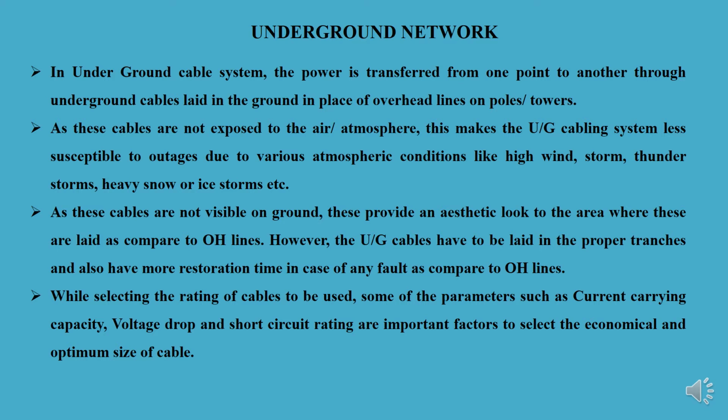However, the underground cables have to be laid in proper trenches, and there is also more restoration time in case of any fault as compared to overhead lines. So we have to mark the trenches, excavate the trenches, and in those trenches you have to pass the wires or cables and supply the power.